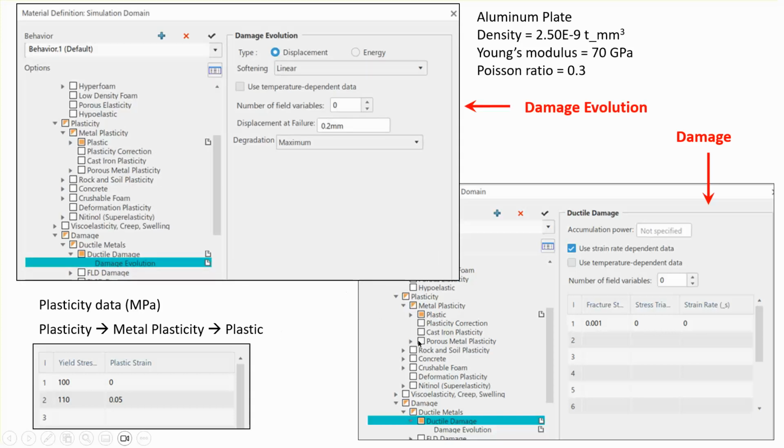but now, in order to also show the damage, basically get rid of the elements and things like that, you also have to input the damage evolution parameter. So right here, you click on the damage evolution, and the only number that the previous YouTuber includes in there is the displacement at failure, which is 0.2 millimeters. Okay, using displacement, not energy, because here you can use two, and there are other options, but I'm just replicating the steps of that reference.